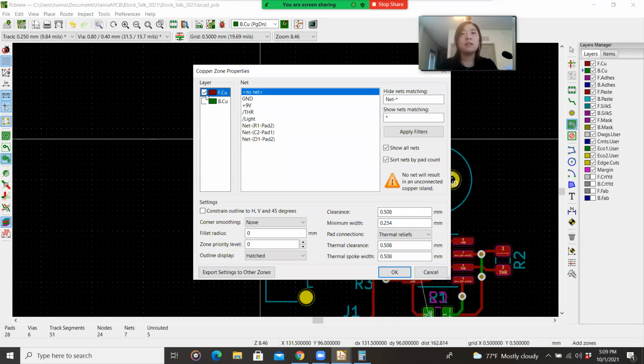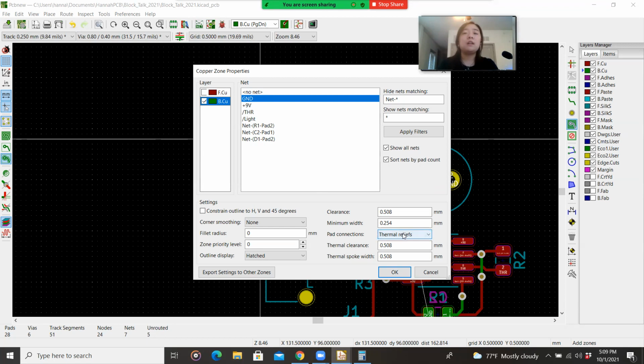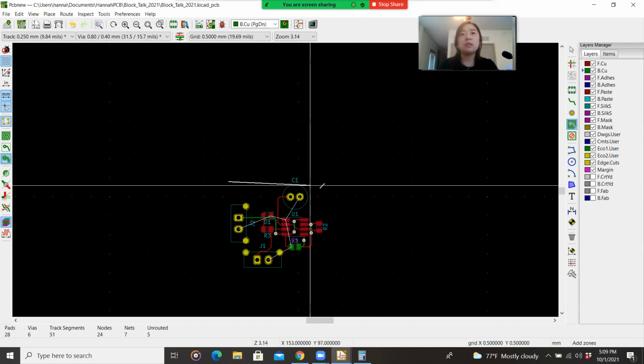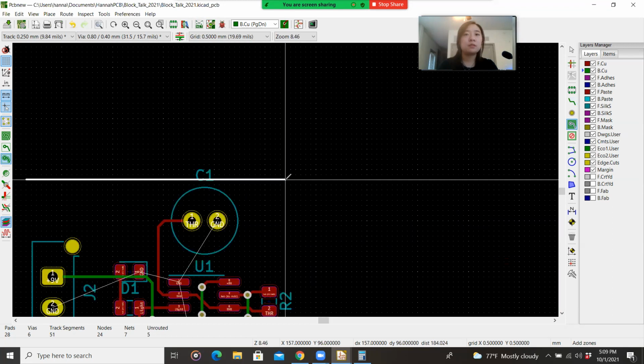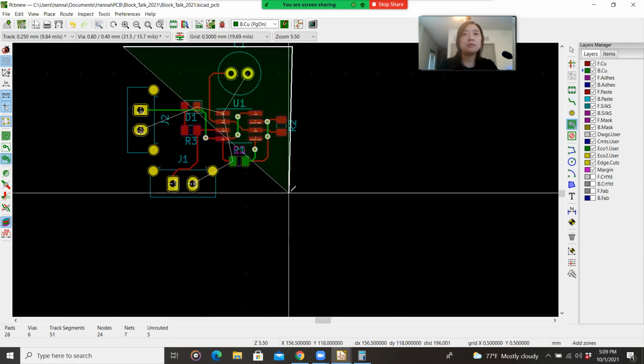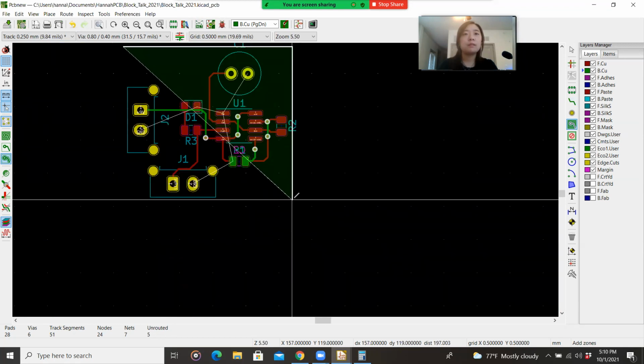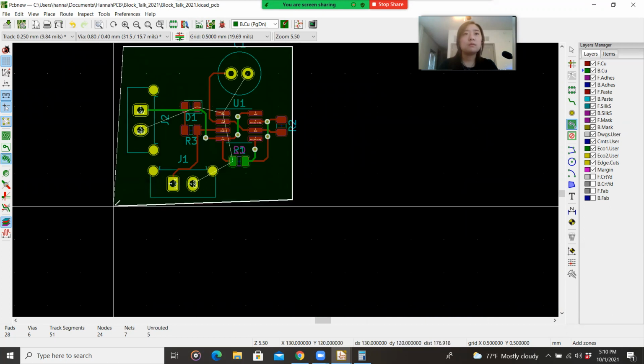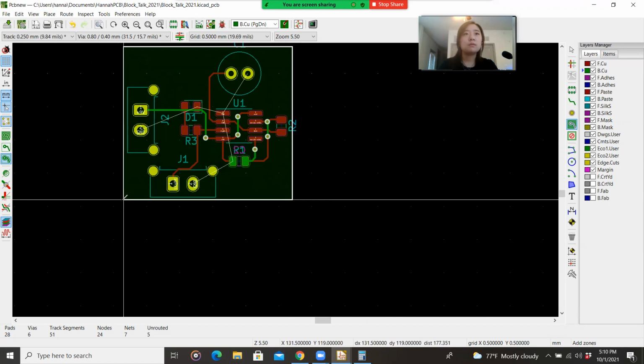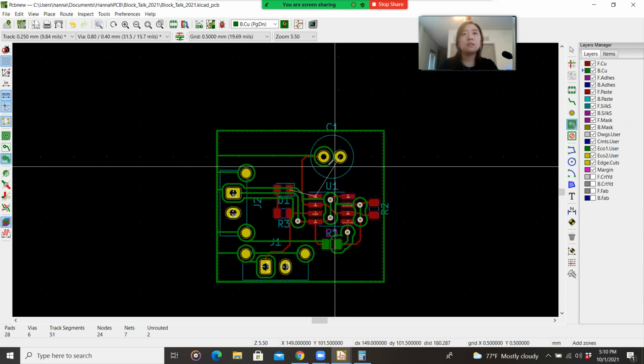Okay, notice, let's go ahead and do one on the front layer, and we can do ground on both sides. Also, if you remember from the data sheet, we do want ground on the back side, because that's explicitly what the data sheet told us to do, and it's good for us to do. So we change to solid, and now we just make a square, or a rectangle. Okay, so notice that you lay the ground plane.